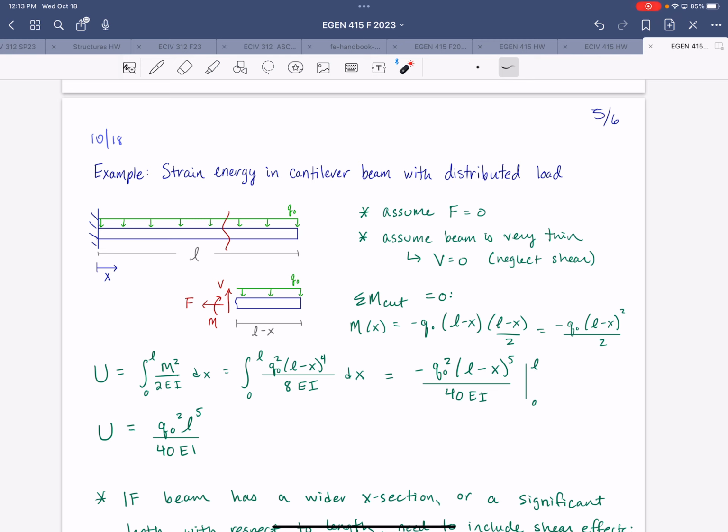And so the deformations, or the energy dissipation associated with that movement, is primarily due to axial deformations, which is the axial from bending, right? Whereas you have other buildings that have a significant amount of shear deformations. An example of that would be the Sears Tower in Chicago, essentially a bundled framed tube structure.